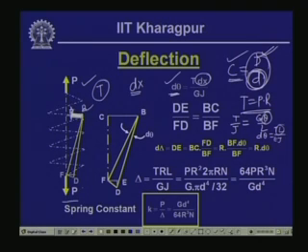Now, because of this rotation of segment AB, the point F of this load point will undergo a movement, and let us call this movement Fd. Basically this movement will be along an arc length, but since AB is a small segment, we consider that Fd also will be small, so that Fd is perpendicular to this length BF. This is exaggerated in this figure.